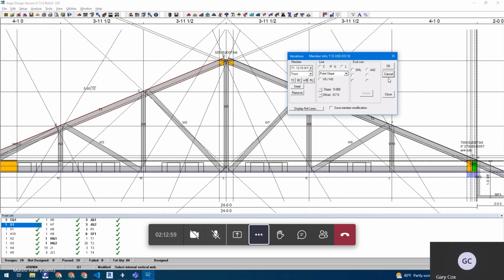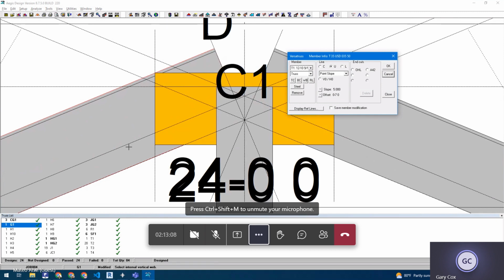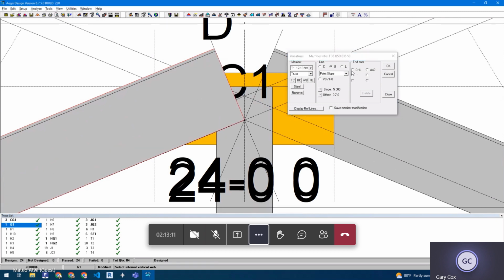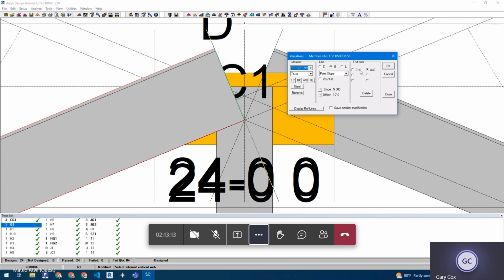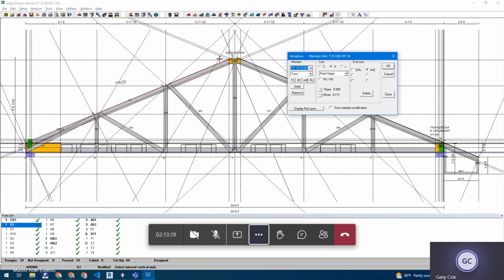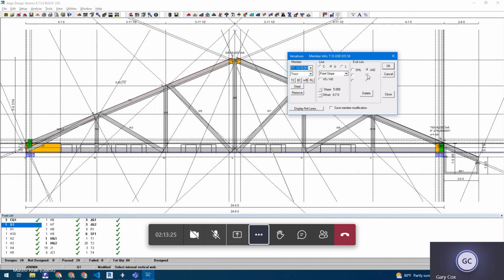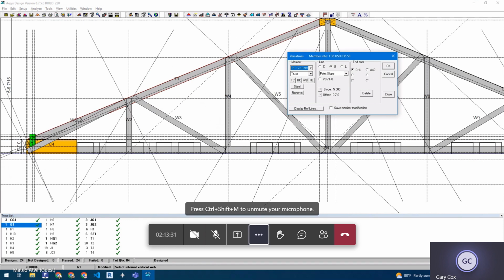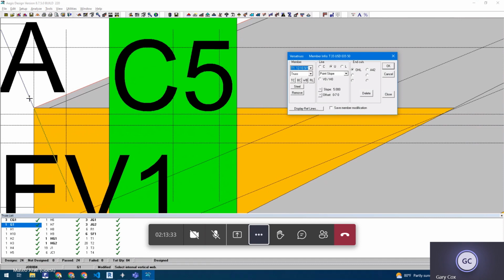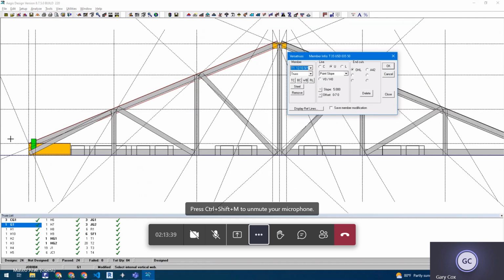Okay. And then in this section over here is the end cuts area. What lines is that member cut at? So you see 2 numbers, okay? There's an imaginary line that represents right and left running down that. So you're allowed 2 cuts on each end. The line it's cut at on the top end is A42. At the bottom end, it's cut at overhang left. There's a predetermined line called OHL. So if you added an overhang back on, it would know to just extend it automatically.